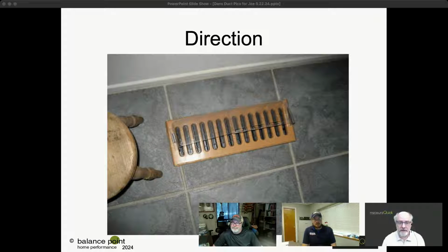Do you ever go to a house and realize that this actually is a really good design? Everything is working here except these registers were the wrong style or poor design. Is that ever an option? We could probably just change the registers out and get a better supply here, or more airflow or a better direction. Some technicians don't even realize that. They think the whole system is a problem when it may just be the termination. It could just be that, or even just the noise it's making. You can make it a little bit quieter by putting the right register in.